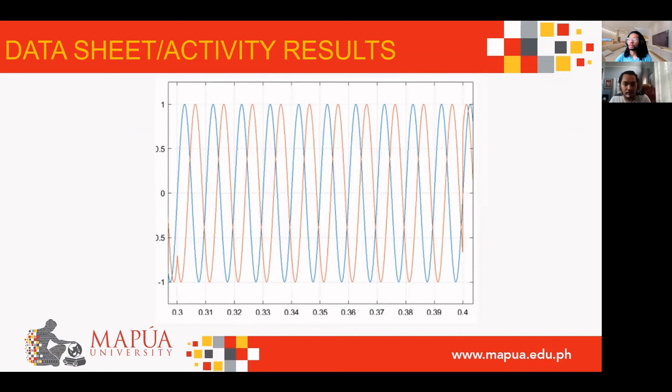And for the next pattern at 0.4, the LSB has already finished its first cycle, which is why it rises to 1 for its second cycle, while MSB is again starting another cycle, which is why the 2-bit code comes back to 11, and the pattern continues on from the following values 0.5, 0.6 up to 1.